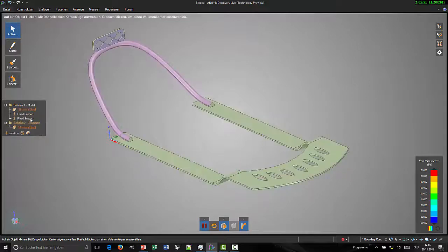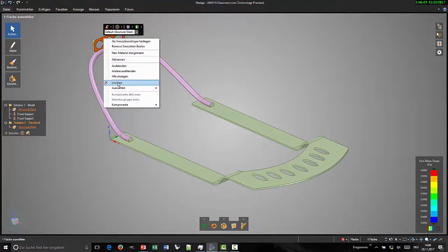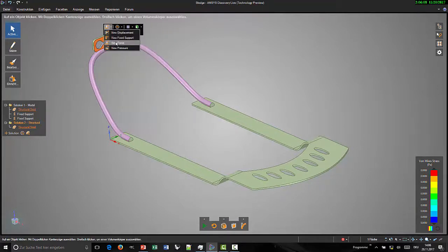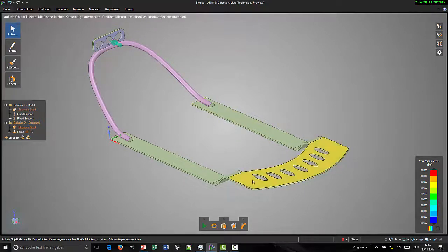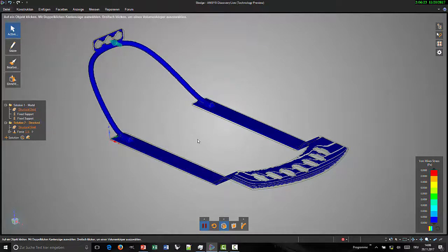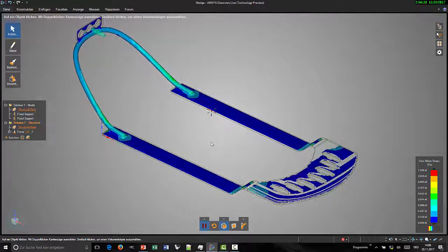You can also make here stress analysis, so you can put some boundary conditions like forces on some parts here, and I will also put it at the front. So if somebody would be pulling this part of the structure, and while doing that, you see here I have to select the correct button, and in this case in the X direction, I simulate a pulling on this part of the structure, and while running this numerical simulation really interactively, I get an idea again on how the structure behaves and where are, for example, the stress concentration points.